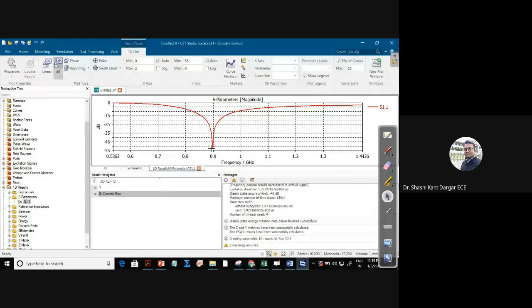This we observed here. Now, can you see one interesting thing, that what we are observing here is not 1 gigahertz. We defined it for 1 gigahertz, we wanted to see it for 1 gigahertz. So it means there is some problem with our dimensions, L, D, whatever we messed up, right? So it means the length of the dipole is not properly chosen. So let me do some correction for this.